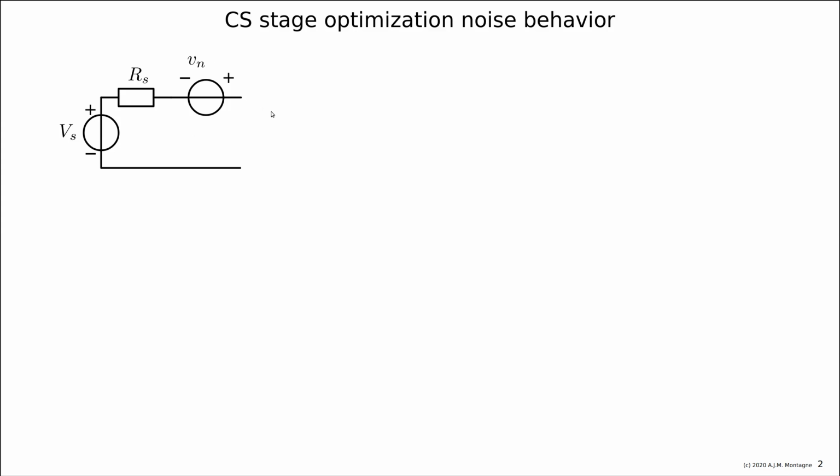And the question that we are trying to answer here is the following. If there is an optimum for the noise, so if we can design the FET in such a way that we have the lowest possible noise, the best possible noise figure, then if the requirement demands a better noise figure, we found a showstopper, which means you cannot design it in the process.